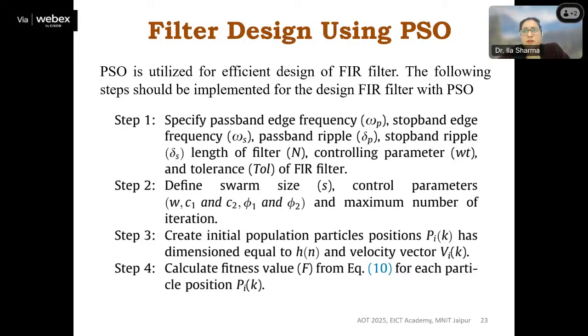My parameter of optimization here is the filter coefficients, and I am looking for those coefficients through which I can make my objective function give the minimum value. So I have a set of parameters. Let's suppose I have specified my filter order to be 10. So definitely how many coefficients will be there? There will be 11 coefficients. And if I am taking the symmetric case, how many coefficients will be there? 6 or 7?